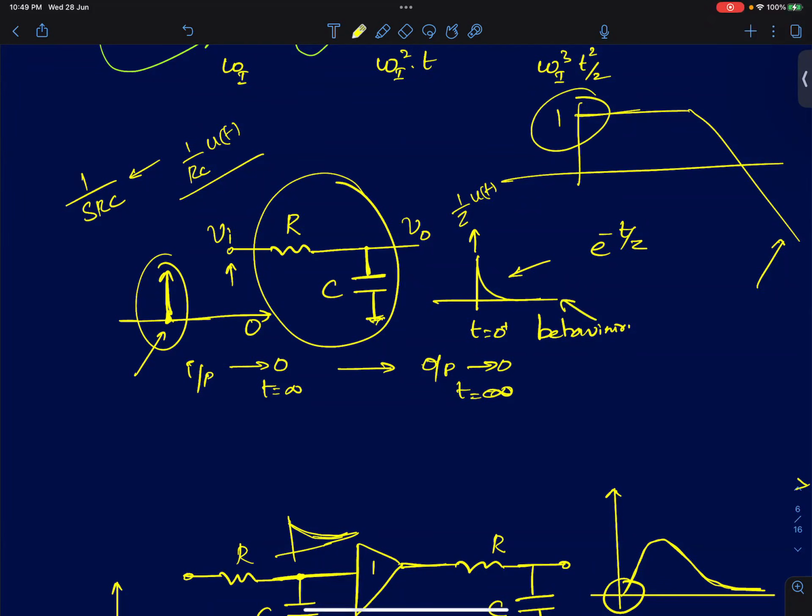It's a first order system. We know it starts at 1 by tau and eventually it goes to 0. So you can just draw the response with the knowledge of how to draw waveforms for first order systems. I've already discussed this before, so I'm not going there. I'd recommend you watch the initial lectures on how to analyze first order RC circuits. But here the point I'm driving home is how to predict the output from the frequency response graph.